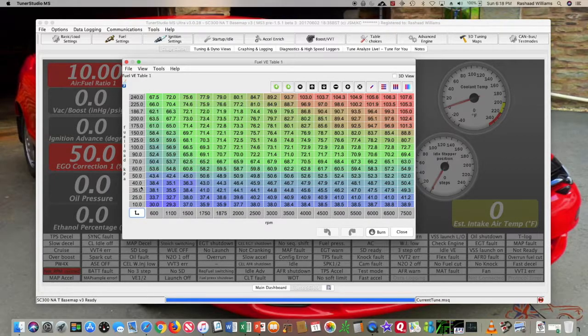You want to make sure you have enough space down at the bottom to catch your idle, as well as enough up here to make sure you're able to accurately measure your peak boost. And you maybe want to have a little bit on top in case the engine overboosts a little bit, as well as having your RPM down at the bottom. And yeah, my red line's at 7,000, so I just went 7,500. So again, a nice little bit of buffer in case I do over rev a little bit, which I don't plan to do. And again, this table is still really rough.